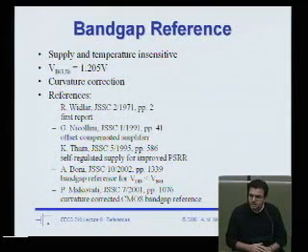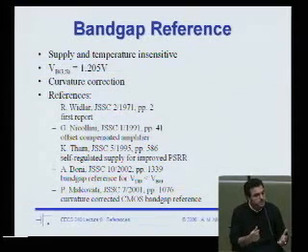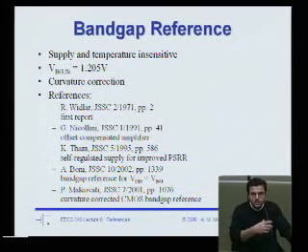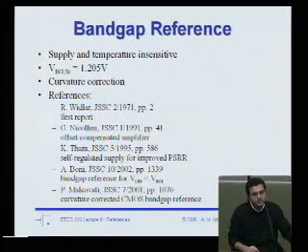So in a bipolar transistor, as we increase temperature, its VBE gets smaller. So if I could somehow sum a VBE, right, I could design a VBE reference current source, do a VBE over R, but that would give me a negative temperature dependence. Well, this PTAT gives me a positive temperature dependence. So if I just sum them together, I could get zero temperature dependence.